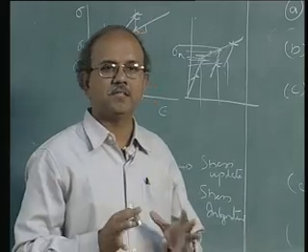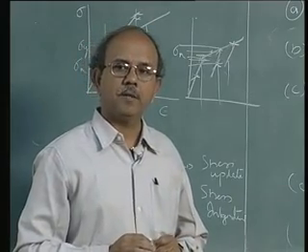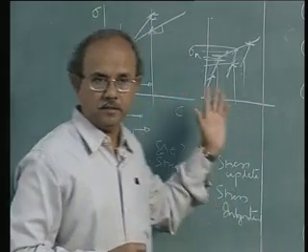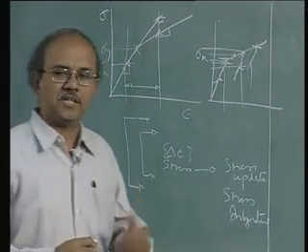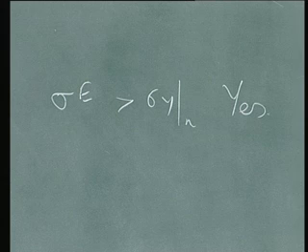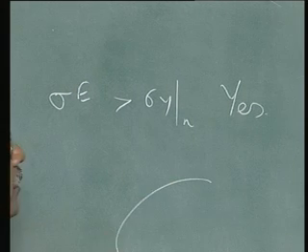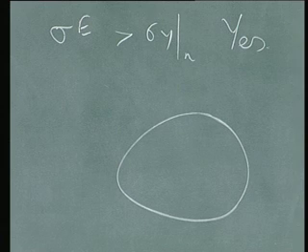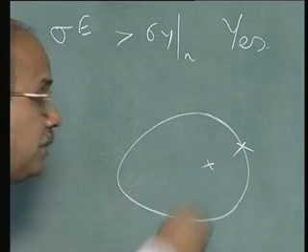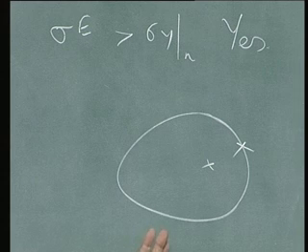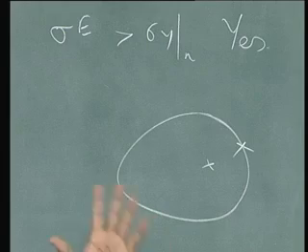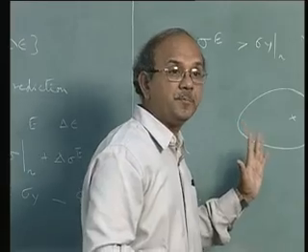This is what is called the consistency condition. In the multi-axial case, already you know what is yielding, so we are going to define a yield surface. And we are going to say that a point will lie either inside the yield surface or on the yield surface. A point cannot lie outside the yield surface. It has no meaning in what we call rate independent plasticity.